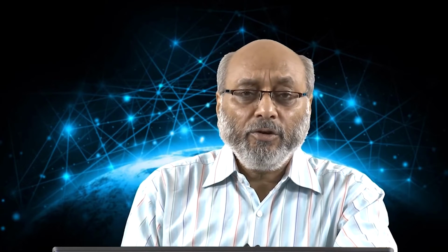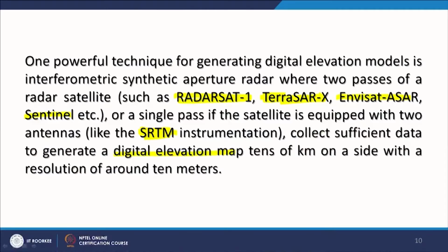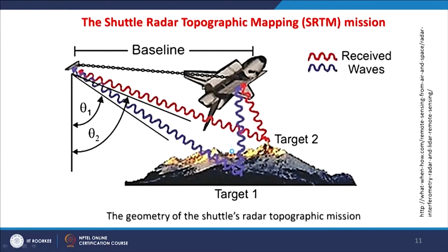So nowadays there are a lot of choices. As I said earlier, now Sentinel data are available, and many ENVISAT and Sentinel data are available free. So one can download the data, that is the radar pair, employ this SAR interferometry technique and develop a digital elevation model of relatively very high resolution.